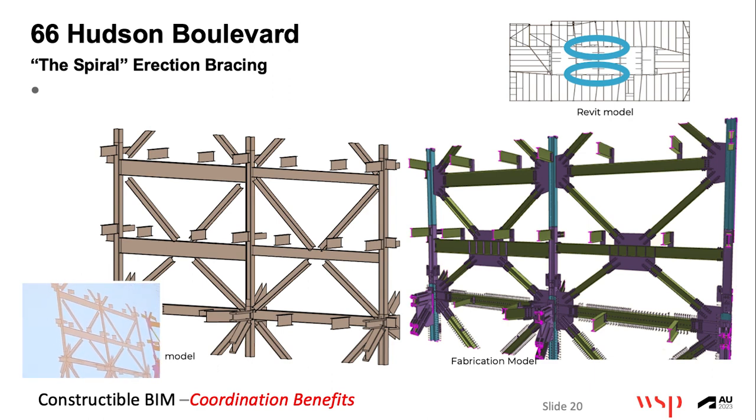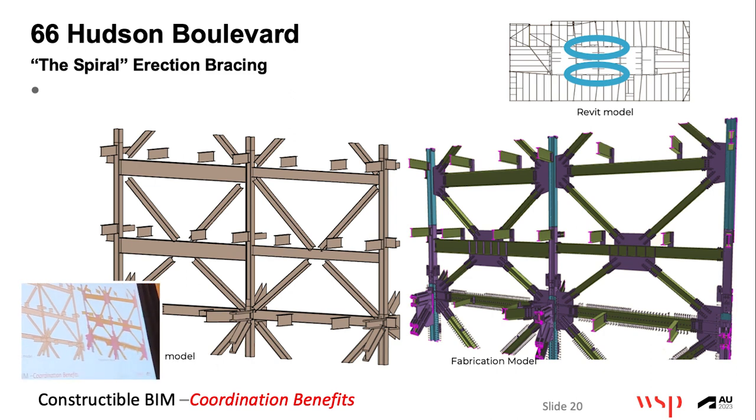More trusses. And again, the complications of these jobs are many different aspects. The beams don't connect. These braces, what you see here, are really temporary bracing systems. They're embedded in the concrete core, but that's neither here nor there. During erection, the filler beams are sitting on the steel. They're not connected into the body of the steel.